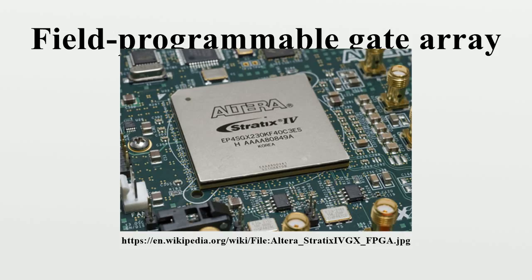More recently, FPGAs such as the Xilinx Virtex-7 or the Altera Stratix 5 have come to rival corresponding ASIC and ASSP solutions by providing significantly reduced power, increased speed, lower materials cost, minimal implementation real estate, and increased possibilities for reconfiguration on the fly.